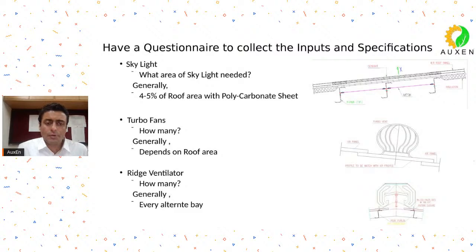Turbofans, for proper ventilation and for proper air exchange, we provide turbofans. So, how many turbofans are required? You should ask your client. It also depends on the area of the roof. Ridge ventilators, again for proper ventilation, you provide ridge ventilators on your ridge. How much to provide? Generally, every alternate bay we provide it.